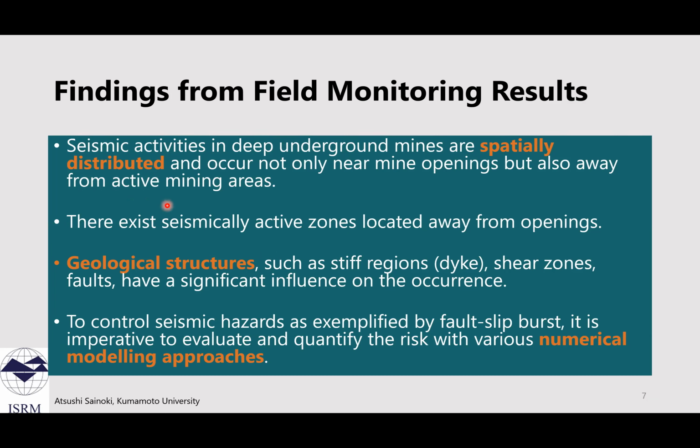And the geological structures such as stiff dikes, shear zones, and faults have a significant influence on the occurrence of seismic events. So to control seismic hazards, like fault slip bursts, it is very important to evaluate and quantify the risk of seismic events with various numerical modeling approaches.